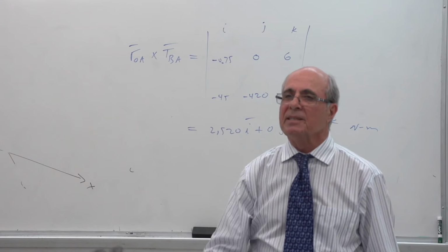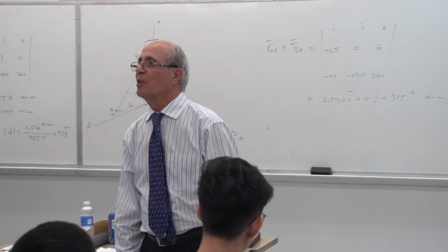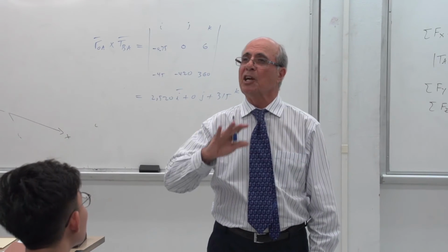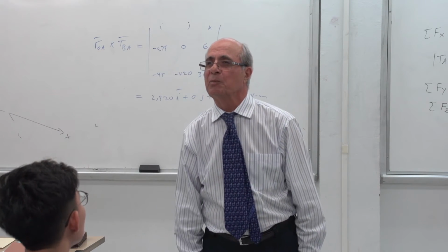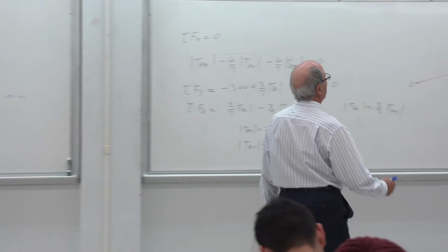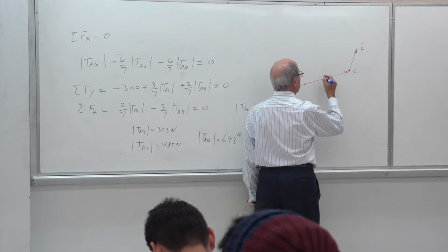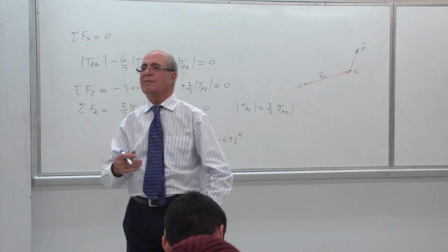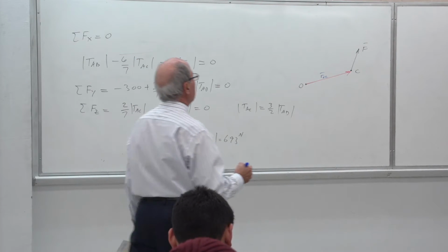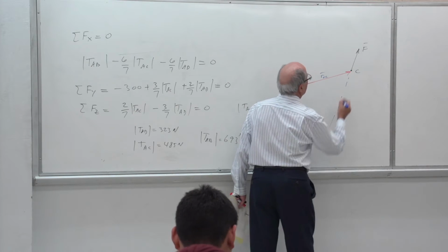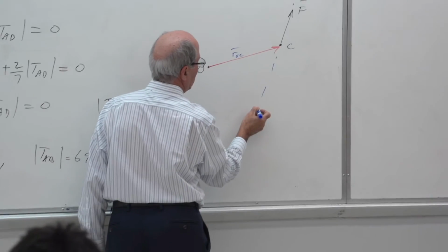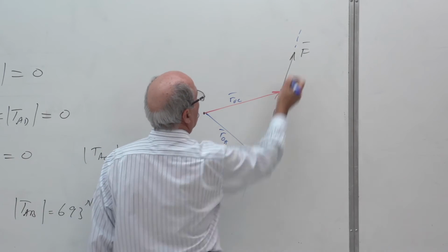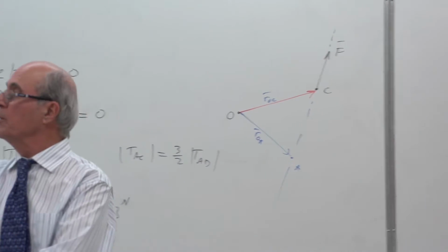What does it mean? That position vector you asked me about a minute ago is not unique. I can use any other position as well. So in other words, this is the story. If this is point C, so far I always said to use this. Is that correct for you? Usually O is given, C is given. However, if there is another point, this is the idea that I presented to you. If this is point A, and instead of that one I use ROA cross product F, I still get the same amount of moment, as shown here.